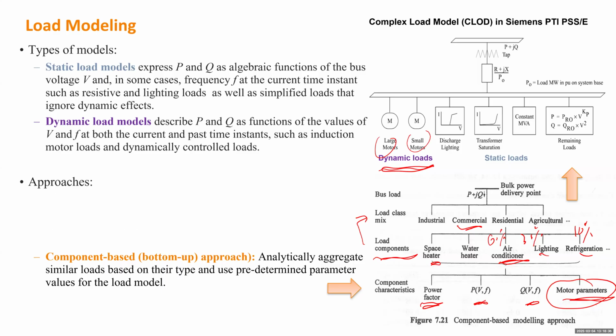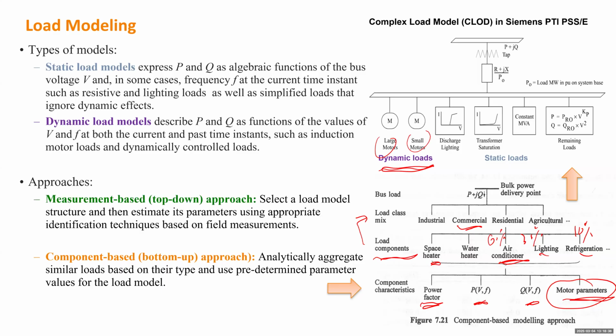So that brings us to the second approach, which is a measurement-based approach. The measurement-based approach is when you already select a load structure, which involves a number of parameters, and you need to collect the measurement data to identify and validate each parameter. You may take an optimization approach by allowing the parameters in the load model to vary a little bit and see which one can fit the measurement data the best. So that will be the final load model.